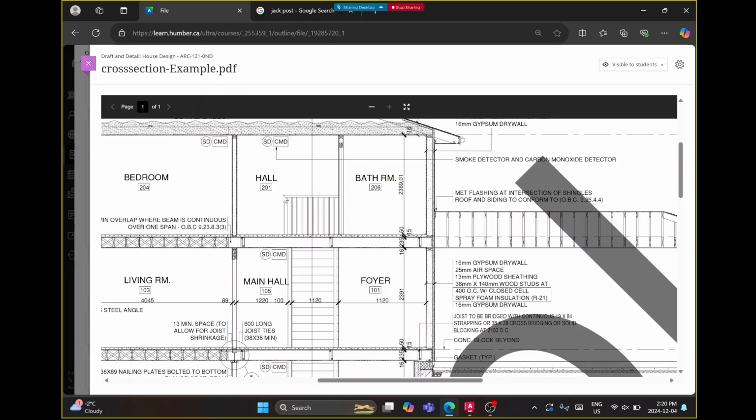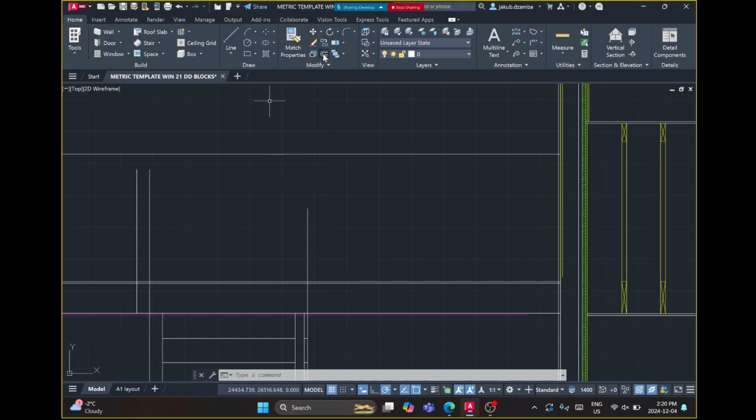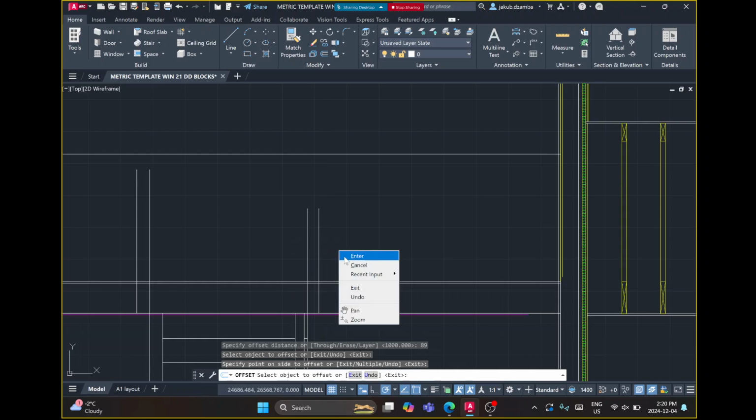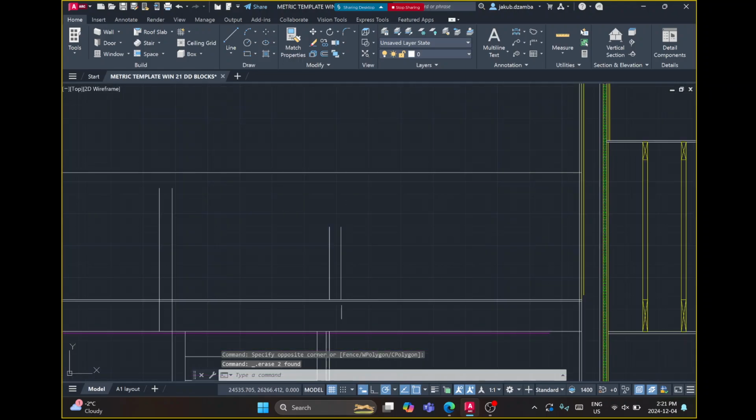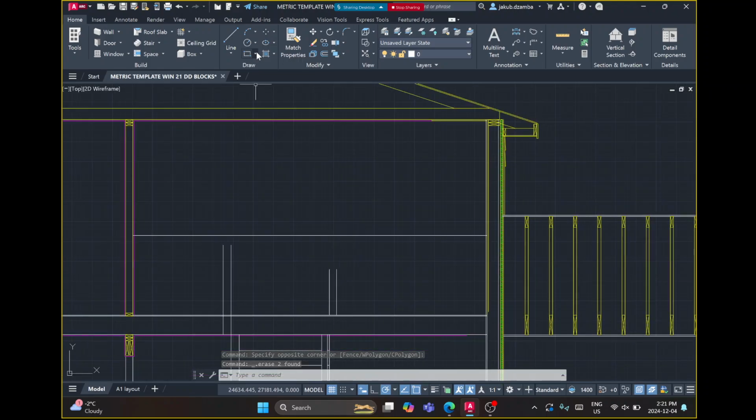They're not showing us. Okay, so they have a railing up top. They have a couple of pickets. Those pickets are usually spaced with 10 centimeter gaps between them, and then they have a wall. So this wall we know is 89 millimeters. I'm going to trim off the extra stuff here. Delete that. And now I think I'll extend this wall first. We have all the information we need to finish this wall.